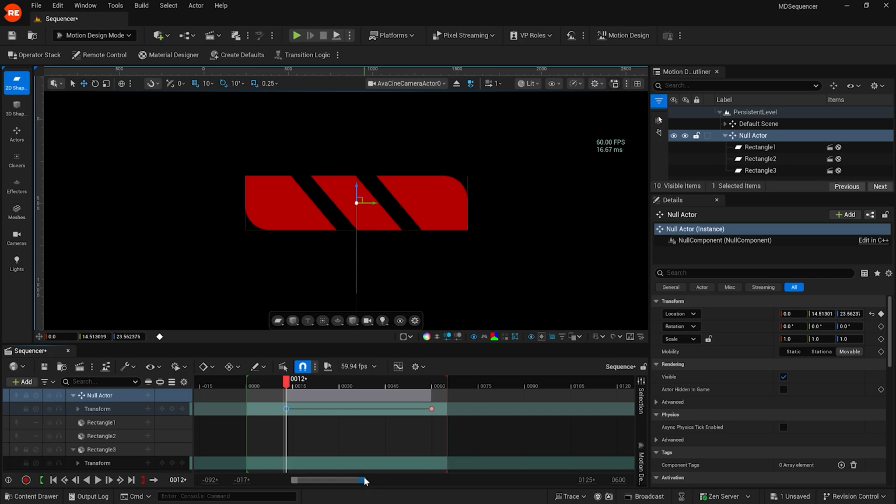The view range in the middle will shrink. You can grab one corner of the view range to increase or decrease the number of frames we see. You can already observe that the view range end time value on the right changes as well. By dragging this bar left and right, you can change the frame timeline area you are working on. However, remember that the duration of your sequence is determined by the green bar on the left and the red area on the right. Green is start, red is end.